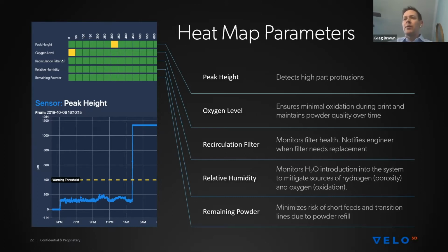So we have a non-contact recoater on the system that basically allows for some deviation of the part to move off of the build plane without having any issues. And oftentimes, even when that happens, you have perfectly good quality material. It's just the part is growing at a different level than the rest of the powder bed. But there's a limit to that. If the part protrudes too far out of the powder bed, eventually you eat into the tolerance you have between the recoating mechanism, and you can actually have a collision on the part.